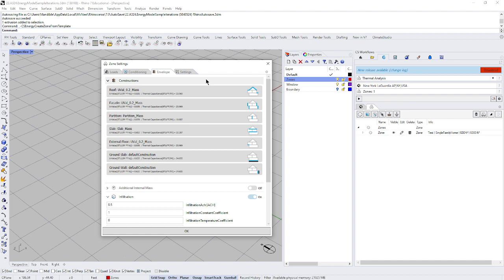What we're trying to do, and I don't think I said this, is the way I presented it: we start by trying to manipulate, I guess, or manage our site resource so that we move as many hours from the outside climate into the comfort zone inside our building, just by how we place the building and things like shading and natural ventilation and placing mass in front of southern facing glass, that kind of thing.